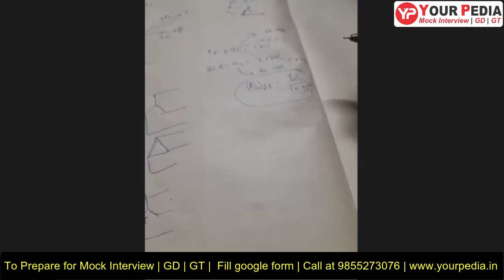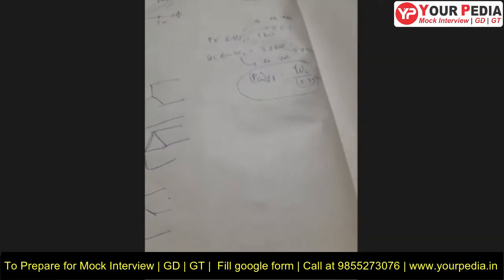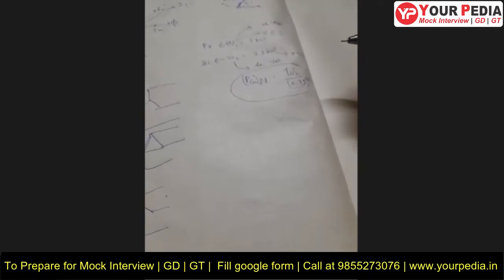Okay. And which is the best? It depends upon which machine you are using, sir. If we are using DC-fed machines such as DC machines or synchronous machines, we prefer open slot, whereas in induction machines, we prefer semi-closed or closed, sir.